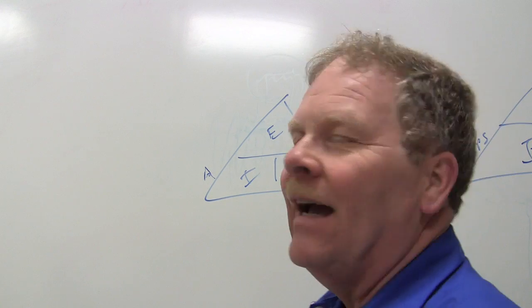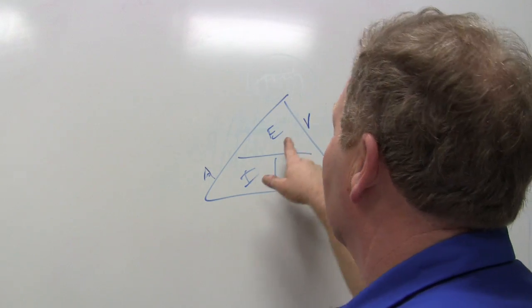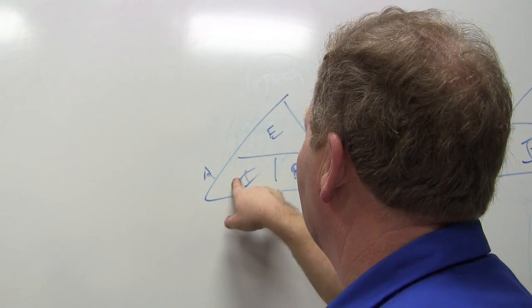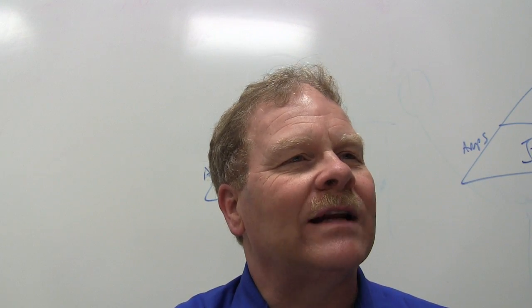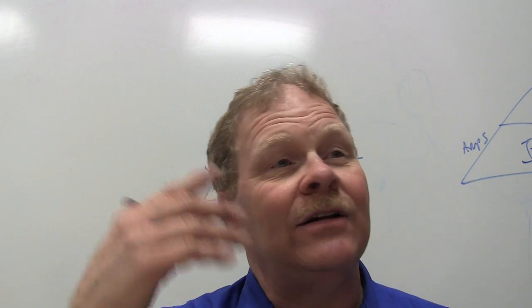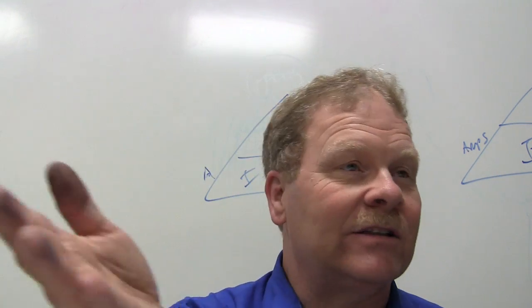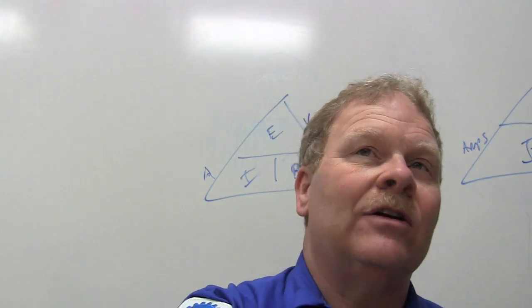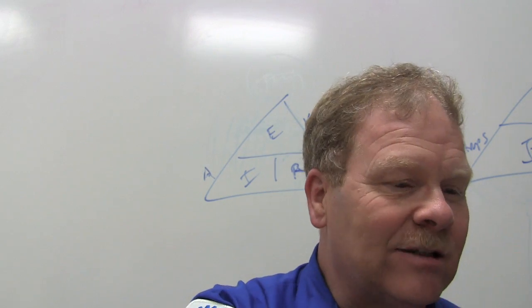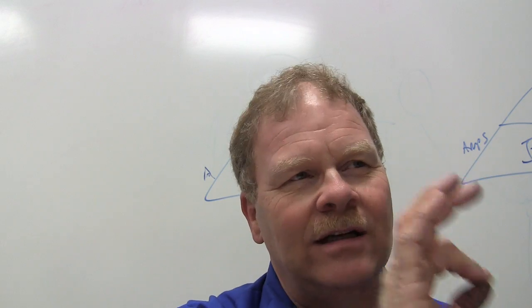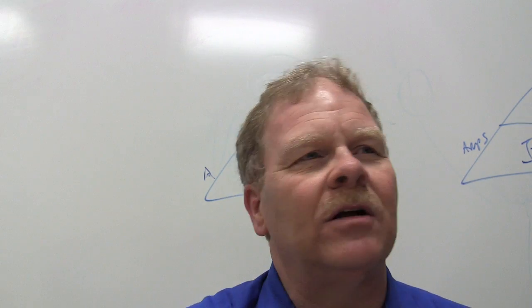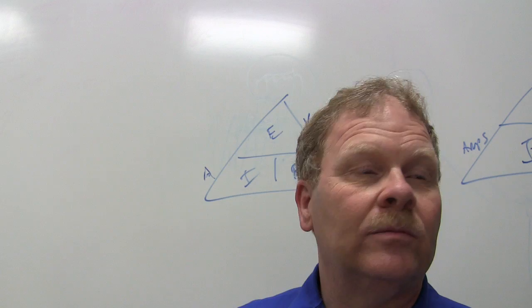Y'all had current times... confused. And if you multiply this times this, you get watts. Okay. So you can figure out what the wattage on a bulb is by finding your power source, how much is there, 12.5, whatever. And then you're gonna find how many amps that thing's pulling by hooking your meter up. And if you multiply volts times amps on the readings you get, you can figure out how many watts that bulb is. Ain't that pretty cool?